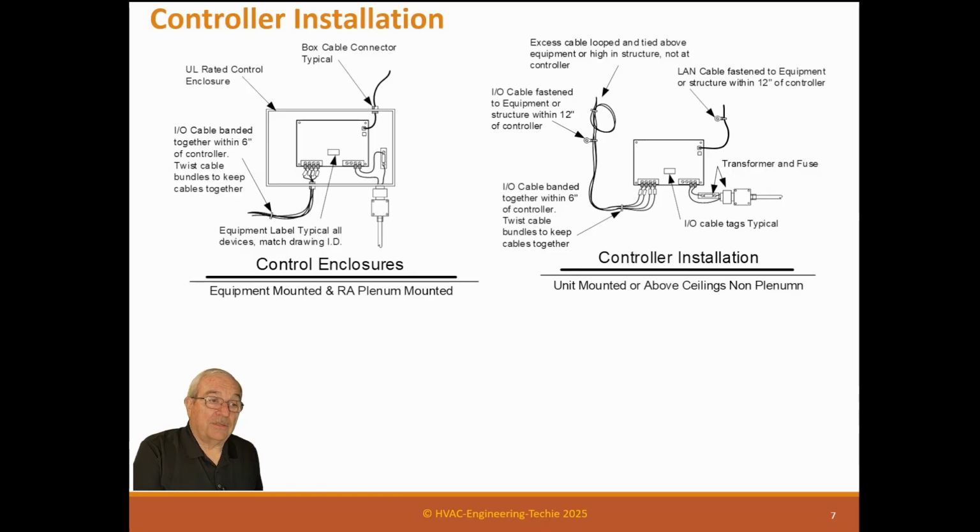So what happens sometimes is a crew goes out and does a rough-in, and they'll pull a bunch of cable and they don't give you enough cable to terminate it. It's too short. You can't have that. You've got to make sure it's long enough. Give them a couple extra feet on the end. Yeah, it's a little waste of wire, but it's much better than having to replace the whole wire because it's too short.